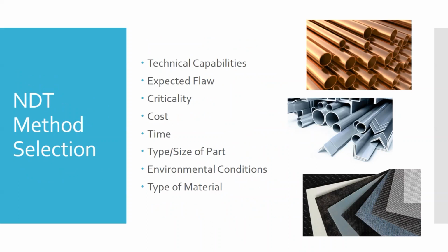You can have a little bit of micro cracking; it's not going to hurt anything. You can use a less sensitive, less expensive, easier to do method. The fan blades I talked about last time, it's super critical you find it. You have to use that eddy current test to find the cracks before they're big enough to find using liquid penetrant. So criticality plays a role in it.